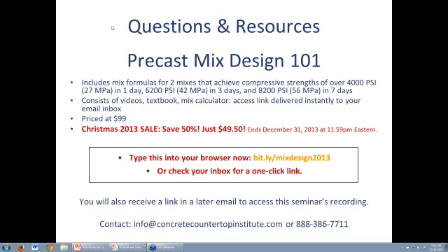And the last question is, where would you use Class F fly ash over Class C? It's usually not a case of when you would use one or the other. Different coal sources create the two different classes of fly ash, so it's more of a question of where are you and what can you get. Class C fly ash has a higher self-alkalinity, it has a higher calcium oxide content. So it is somewhat described as semi-self-activating. Don't get excited. That doesn't mean that you can make 100% Class C fly ash concrete and have any kind of remotely high early strength at all. It just means that it has slightly different chemical composition.